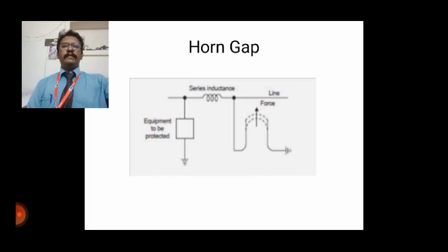Next, whenever a surge voltage exceeds the breakdown value of a gap, a discharge takes place and the energy content in the rest of the wave is bypassed to the ground. An arc is set up between the gap, which acts like a flexible conductor and rises upward under the influence of electromagnetic forces, as normally happens in the diverters. This increases the length of the arc, which eventually blows out and won't sustain.